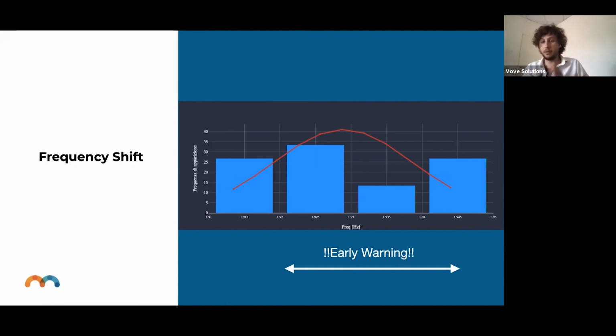So the frequency means that, for example, let me rephrase that. If you get a frequency at a certain hertz, okay, let's say it's the first mode, you wouldn't want to see a change. It can change due to environmental things, but then it shouldn't change much, right? So we should see it narrow, okay? But here in this case, when they monitored, they saw that in just a couple of months it was changing too much, too fast. That was another signal that something was wrong, okay?